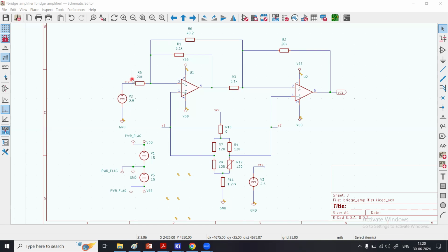So as you can see, we can model a sensor, which is a strain gauge, using this variable resistance here. I have four resistances, 1, 2, 3, and 4, arranged in a fashion that makes up a Wheatstone bridge, a popular Wheatstone bridge. At the junction right over here, I have an external voltage supply labeled as VEX, and that VEX is coming from this DC voltage source, which is set to 2.5 volt.